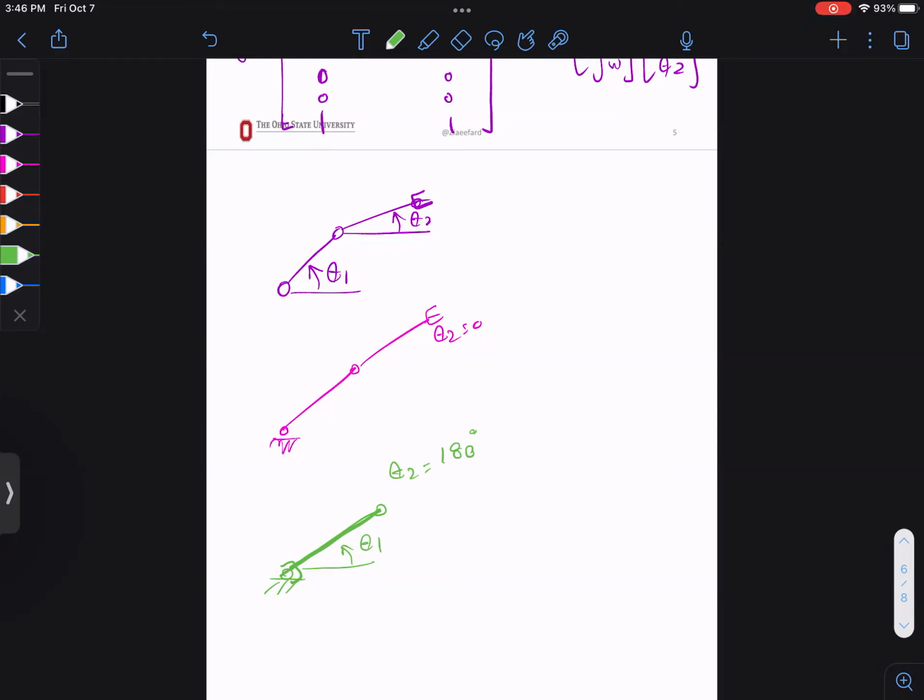So singularity is when the end effector loses a position or an ability to move, right? A case could be losing a degree of freedom, or in this case, it does not move at all. If this was an actuator, it doesn't matter how much it moves, the end effector doesn't move. Sometimes you see that, especially if you're familiar with the gimbal effect: when two axes align, you lose a degree of freedom because nothing will change, right?